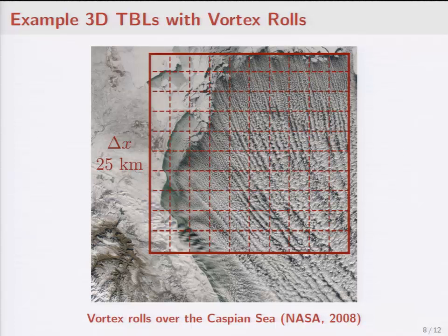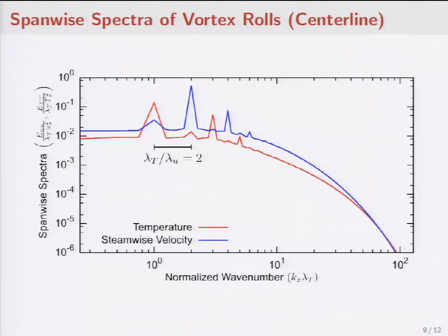So this is a classically well-known example that when you grid, say, in turbulent flows, you very often have smaller spanwise spacing, because these organized structures are preferentially aligned in one direction rather than the other, and to resolve them, you need to consider this effect. Okay, so like in the example I showed before, because this is a very large aspect ratio domain, to be able to resolve these large-scale organized structures, we want to be able to see what's necessary.